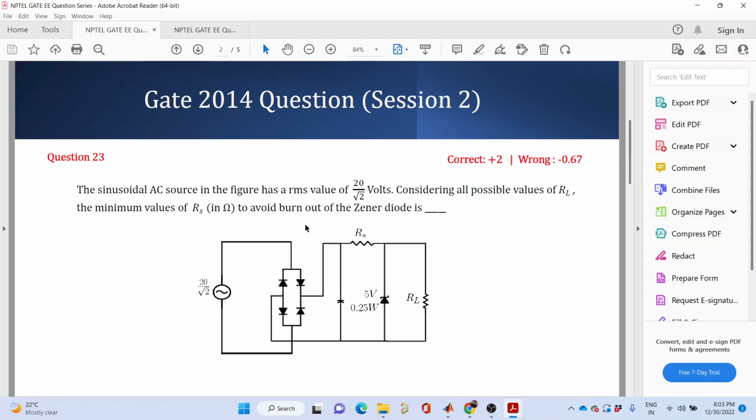Using an inductor. So another simple, low cost remedy would be connecting a resistance in series with the source. You connect a limiting resistance in series with the source and let the capacitor charge. Once it is fully charged, you short that resistance. Right? You got the point.